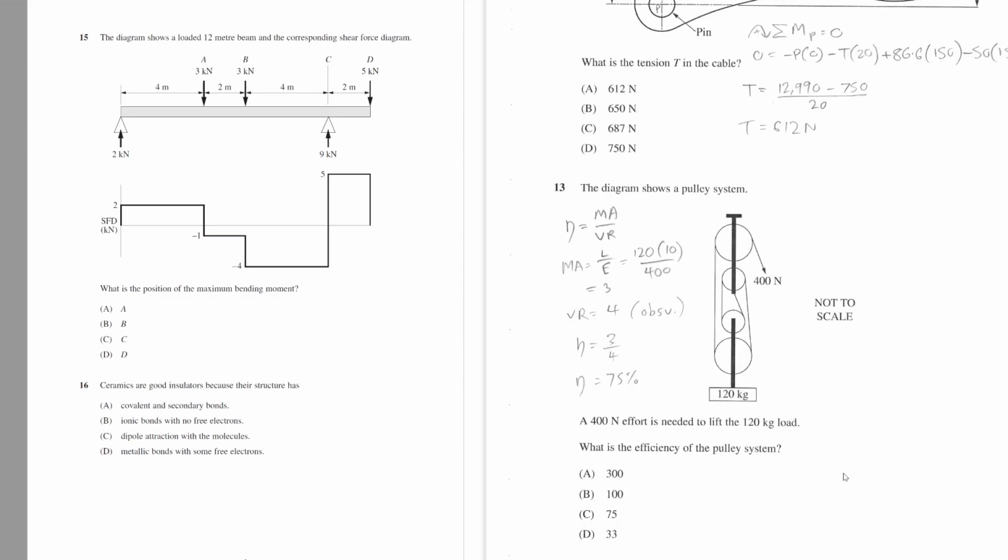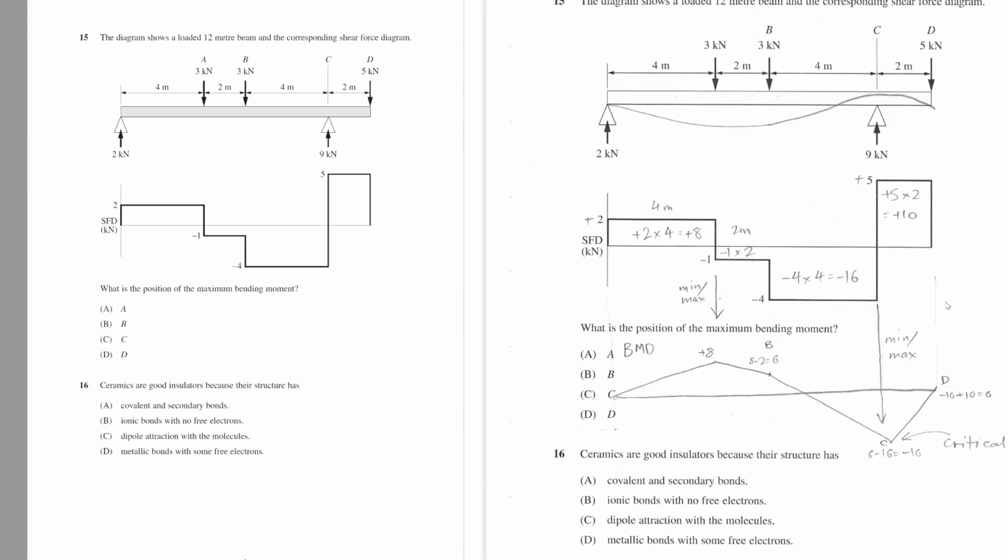Okay, so for question 15, the first thing I did is I looked at the forces here, and I said, okay, what is this beam going to bend like? And this is something I learned at uni, you look at how this beam is going to bend. It's going to bend in this sort of shape. My bending moment diagram is going to be the exact opposite of that shape, right? So this one here, it's not going to be curvy, whereas this one here is curvy, but the same idea, it's going to be the opposite shape. Now I can't know where the maximums are going to be, but it gives me an idea, it helps me to understand what shape I'm going to produce.